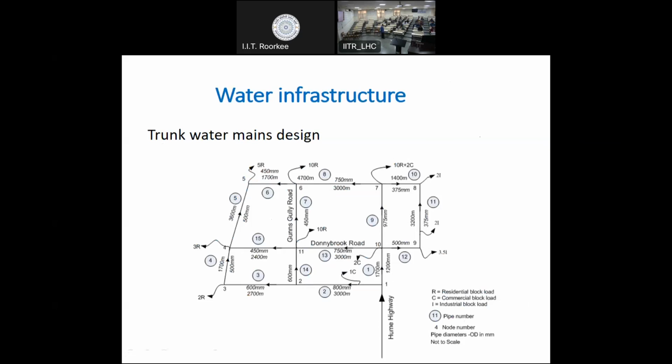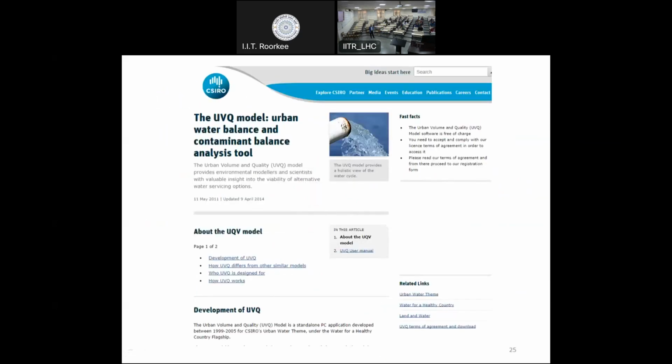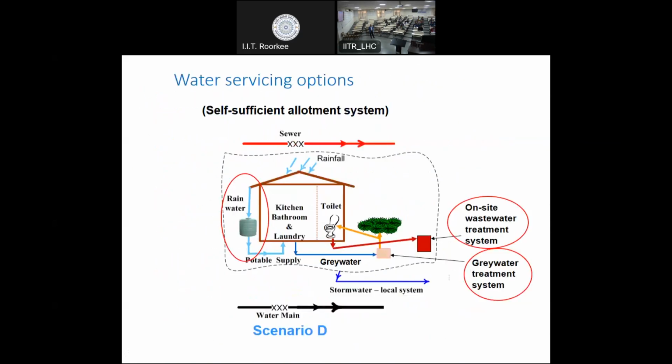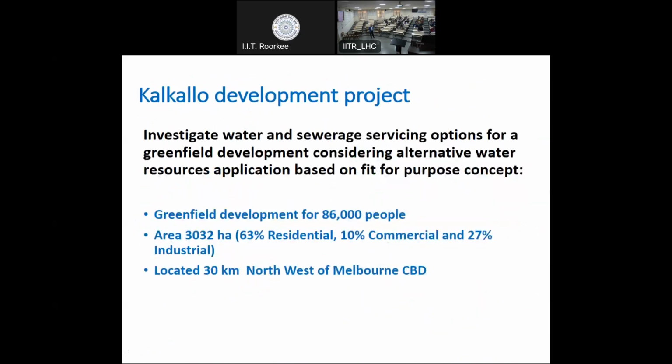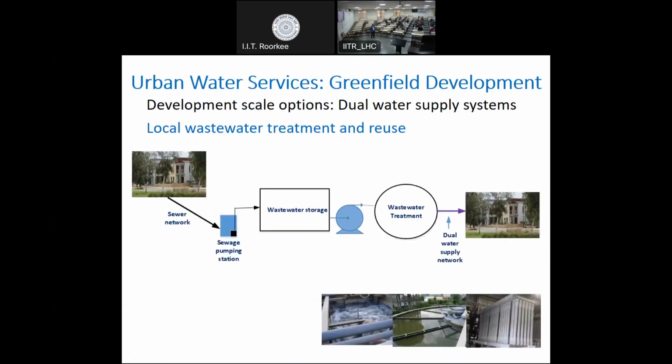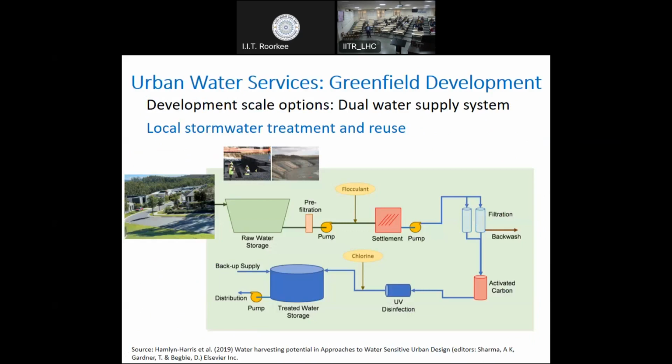So when you have a pond, the storage tank, before that, I think in one of the slides I showed, you can see before this raw water storage, which is the stormwater, we have the gross pollutant traps, which we talked about. That will remove all the initial large particles before it enters the raw water storage. And sometimes even before that, we will have a sedimentation tank too, where the large particles will be removed before entering the raw water storage.